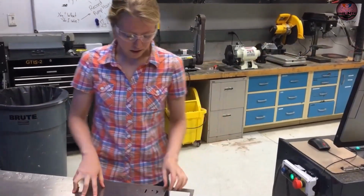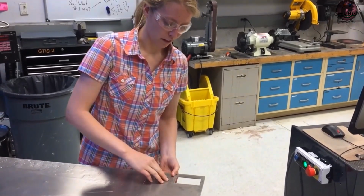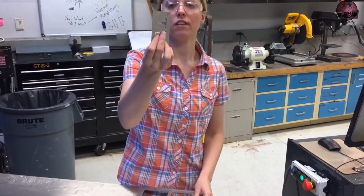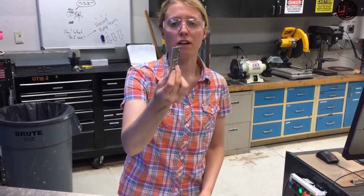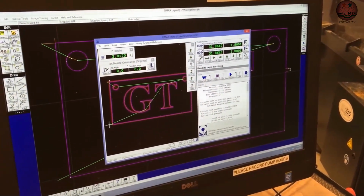Now since your part is still attached to the material because of the tab, you'll have to wiggle it back and forth until it breaks. It leaves a little stub on the material, but you can sand it off or grind it off depending on what material you've used. When you're finished with all the jobs you want to cut on the water jet, go